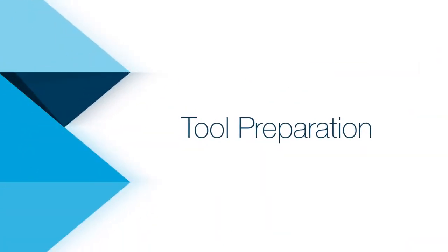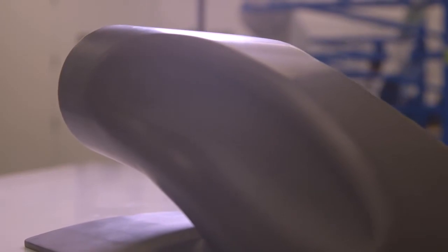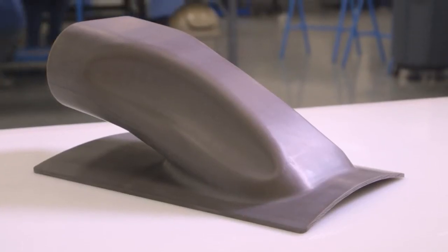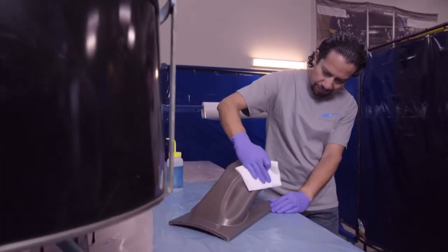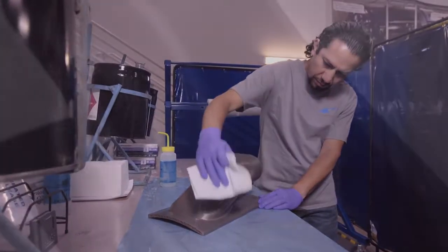After the tool has been 3D printed, we go straight into tool preparation: sanding of any anomalies, perfecting the surface finish, and then applying mold sealer on the tool. And then we would go into application of the mold release. The mold release that's applied allows for part separation after the part has been cured.